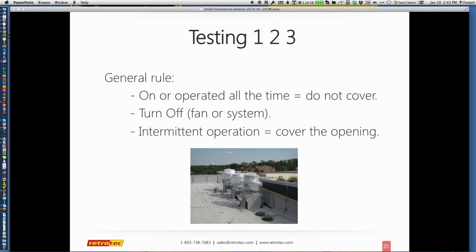Maybe you have a drywall ceiling and it's still an additional roof, but in general, the roof is your actual air barrier for many of these cases, and that's where the insulation belongs. If it's not, you're going to find that they've really challenged where the air barrier is and the thermal envelope, and they really should be in line with each other.